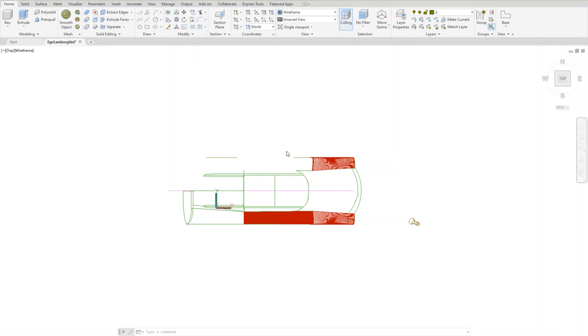I am going to try the mirror again one more time. Click down the arrow and select the mirror command, select the item, enter, and select the first point.